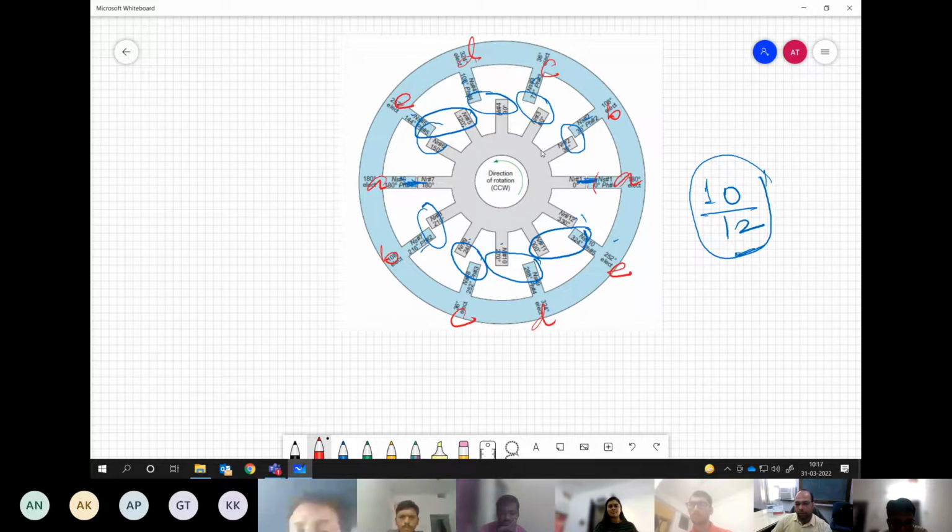You understand, right? With respect to the rotor position, at whatever point it is, you can see that two poles are coming similar. It's not necessary that only two have to be similar. There could be four also. If the machine is designed in a different manner, there could be four poles. So all four will be clubbed together as one phase, say A. The next one, which is looking similar, is this, partially overlapping. So this can be grouped together and called B. There could be more, if they are looking similar.